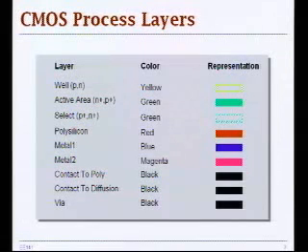And in most cases, it's connected to the source, but you have definitely access to that fourth terminal. And in order to connect that terminal, you basically have to invert your diffusion. So if you have N well, you have to make a connection to that well through N+ layer. And that's called the select layer. So for the NMOS, you have P+, because you have a P well, and for the PMOS, you have N+, that connects your well terminal. And these are normally connected to supply and ground.